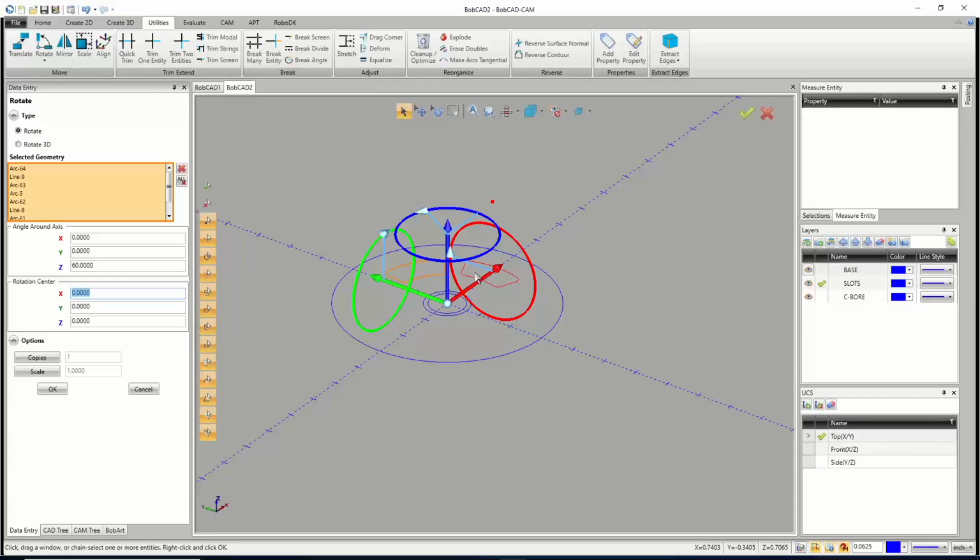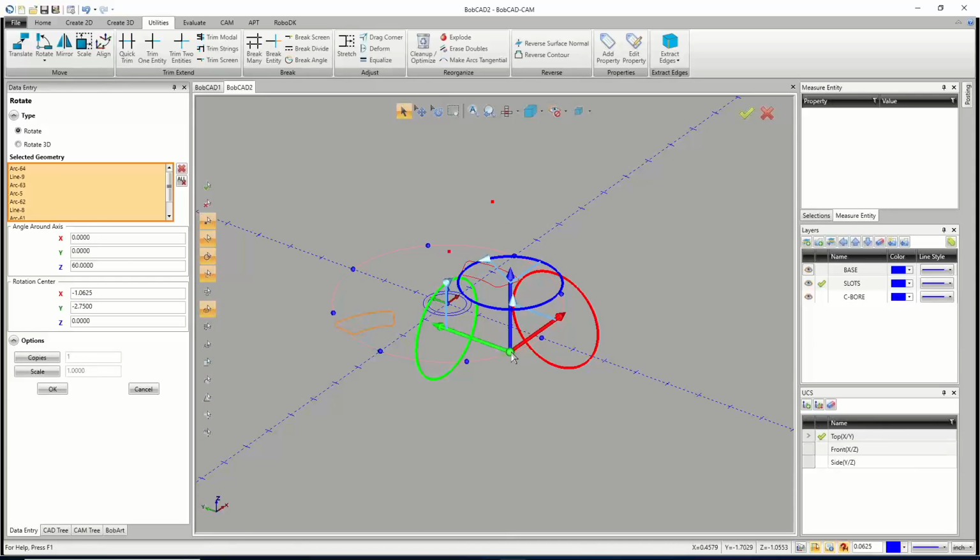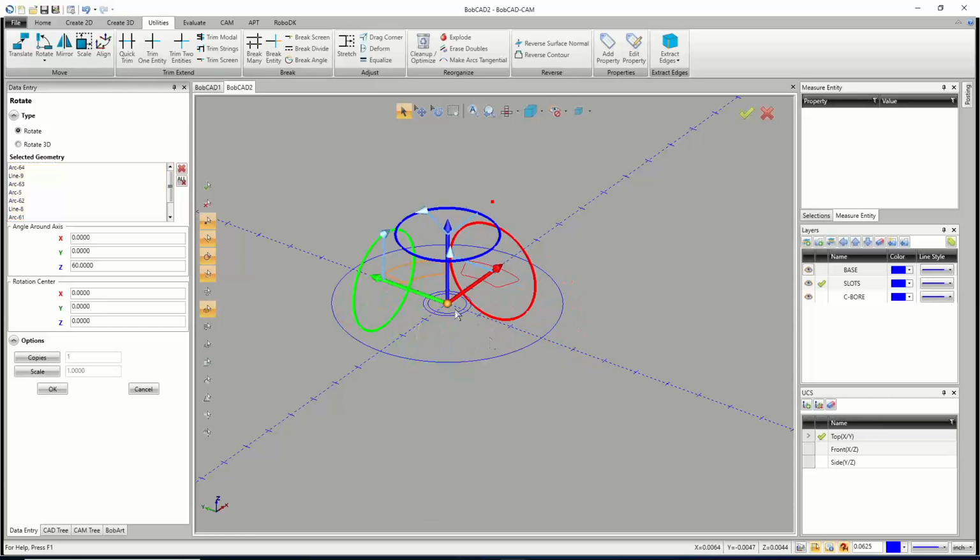It depends on what kind of shapes you're working with. If you're working with arcs, if I go down here, or if I pick this thing, you always have all your snap points. So you can always find the center. But if you're working on like a rectangular part or just an odd shape, you'll have to locate the center. You might have to draw a line from corner to corner on a rectangle and go from the center of that line, and you're just using that line for construction or something. So just play around with it. If you don't know what it is, you gotta pull some measurements, find yourself center. But in our case, this is one of the biggest reasons why I don't draw in the upper right hand quadrant.